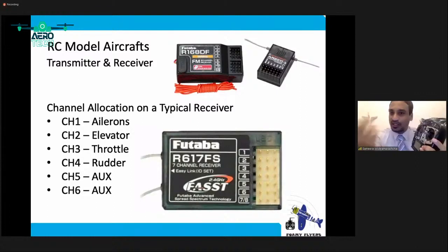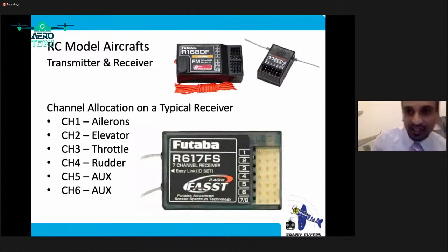So what would an aircraft do? It will power up, right? It will power up to 50%. If you have your arm or anything valuable, or maybe somebody else holding that particular aircraft, that person might get injured. So you need to know that you have connected the cables correctly, and the polarity should be correct as well. I'll get into that.